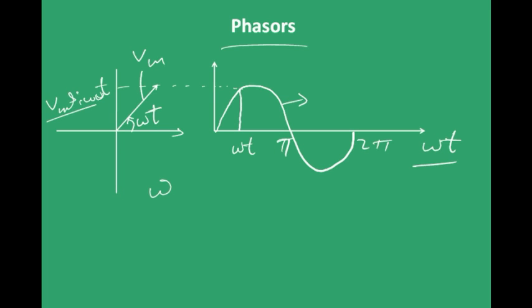This is clear. Now, if I want to represent Im of the previous situation, that is a purely resistive circuit, in this phasor diagram, you know that the voltage and current were in phase, right? So my current will be something like this along this one because they are in phase. Even that has the same time period, but the amplitudes will be different.